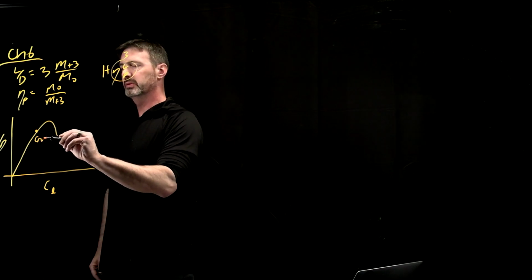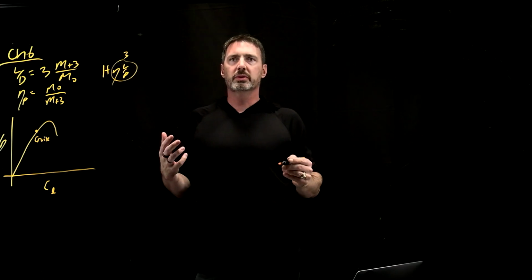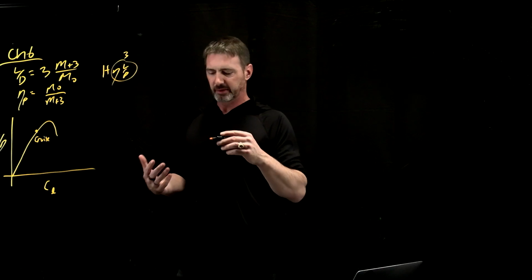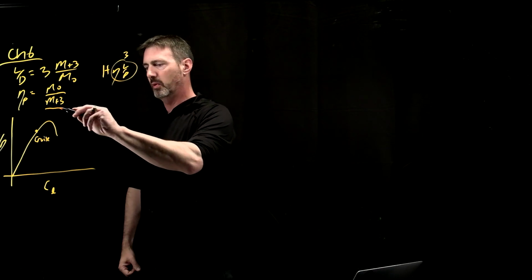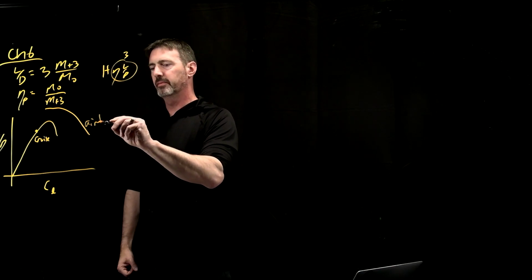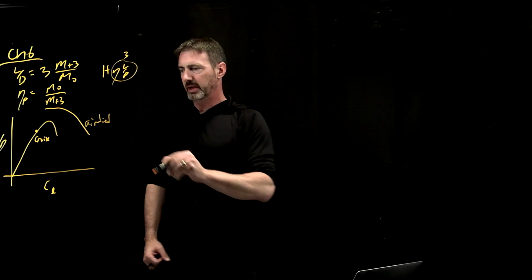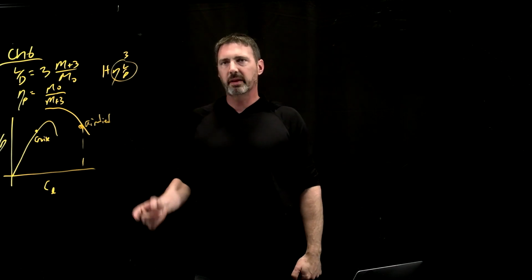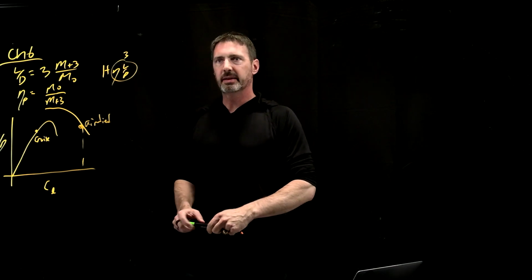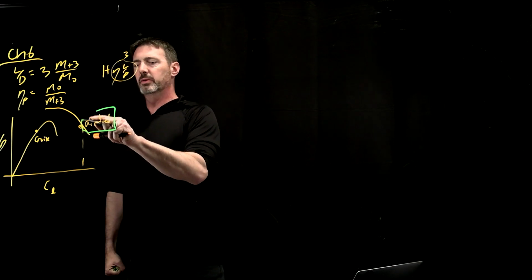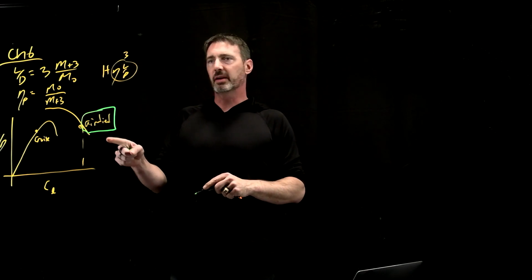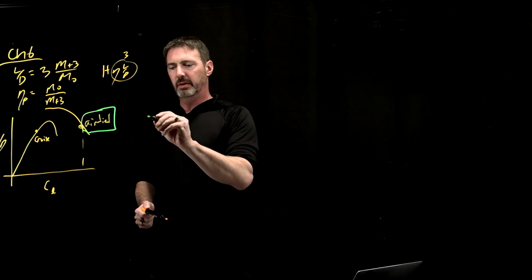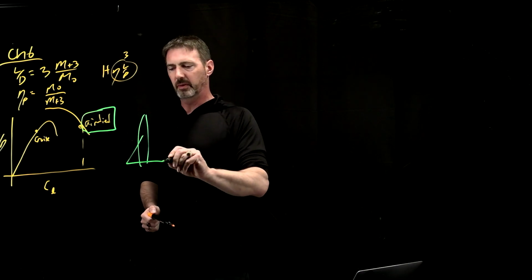Okay, so there's cruise. But then in order to honestly operate out of an airfield, given runway length and things like that, you needed something more along the lines of this airfield. So in fact, you needed this dot on CL for airfield. And so the biggest challenge, as he's framing it, is this one right here, which is how do you design an aircraft that can fly like this out of an airfield, but then cruise like that. And ultimately that's where the slender delta wing aircraft comes from, okay?